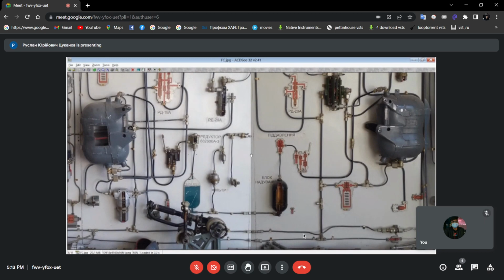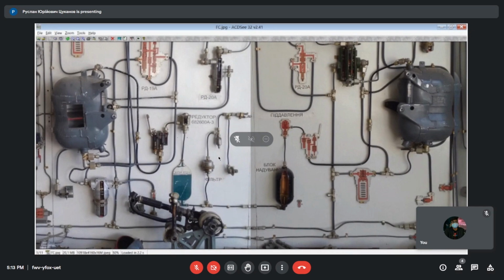I suppose you can see in the scheme, page 9. So the hydraulic system includes 3 subsystems, it's possible to say. The power control hydraulic system, which can be called the boost hydraulic system, in Russian бустерная. The combined hydraulic system, which can be called main, in Russian основная, общая. And the pressurization subsystem. Let's start from the most simple, the pressurization subsystem.